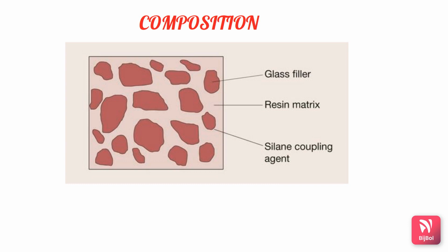The fillers in the composite resin are usually a type of glass such as quartz, silica, and barium glass. They are added to improve the physical, mechanical, and optical properties of the resin matrix. They also help by lowering the polymerization shrinkage, increasing the compressive, tensile, and modulus of elasticity, and increasing the abrasion resistance.